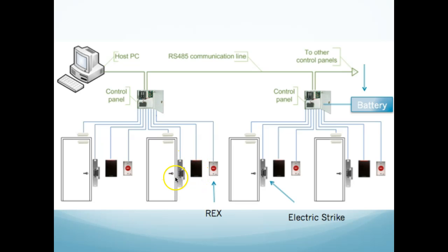It does a couple of things, and we'll study these contacts right here. These are alarm contacts. So just in brief, when you use your badge and it says unlock the door and it sends it down, it does two things. It unlocks the door and then it shuts off this alarm so that when you open the door, you don't send an alarm in to the guy who's sitting here monitoring the host who says somebody just forced this door open. It didn't happen. So it also shuts the alarm off.